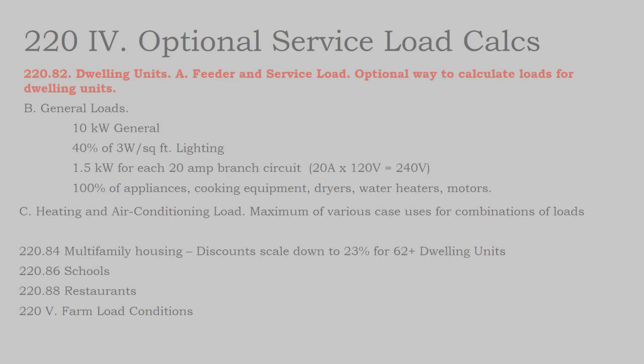And generally, these rules will get you into a 100 amp service for a small unit, and then 200 amp service for a large unit. It also might mean that if we're generating energy on site and we are managing our energy with a battery bank, some of our home electric services are going to start to look pretty oversized compared to, if you're an energy efficient home and you're fine tuning your energy use. You might find that your home is only using 60 amps of power, but you have a 200 amp electric service.